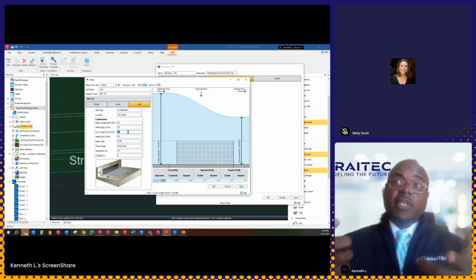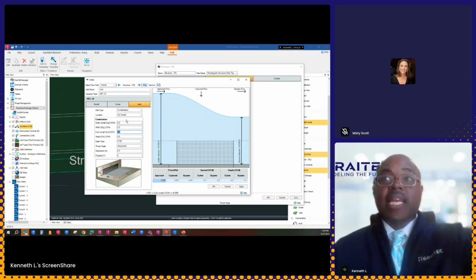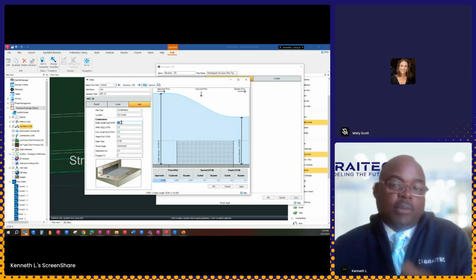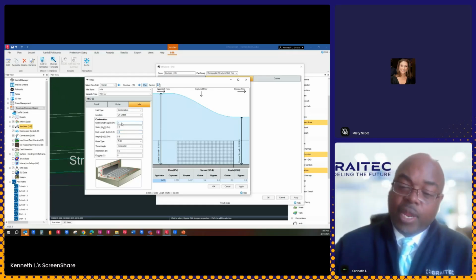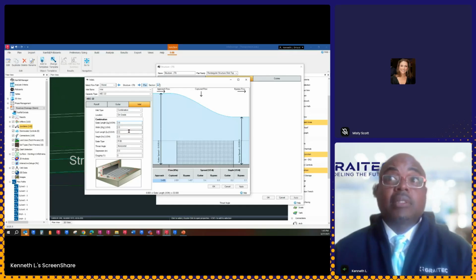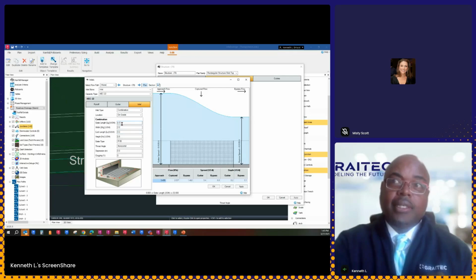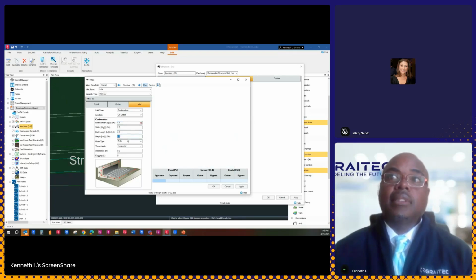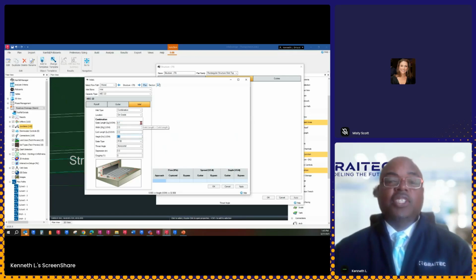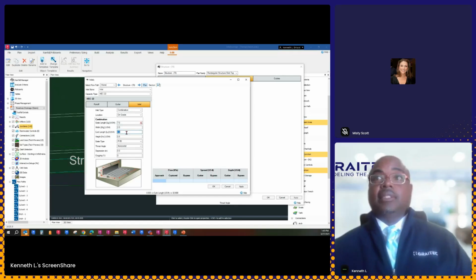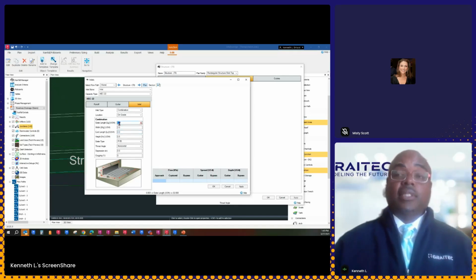Okay, these what-if scenarios. So it says my grade length can't be greater than my curve length. I'm just doing some troubleshooting. Let's say 3.9. Still the same thing. How about 4.1? Uh-oh, now we have an issue. So some really nice tools, and that's with everything in InfoDrainage.